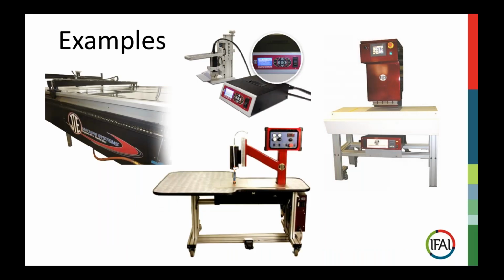So these are some examples of RF welding equipment used in industrial fabrics. The machine on the left is actually a cutting system. Because we have a little bit of core competency in cutting and welding, we developed an XY cutting system that you load the pattern into. It cuts around the pattern, and at the same time, it's welding or serging the edges. This is being used, for example, in an extreme sleeping bag application where they needed to serge their batting in nylon material prior to taking it to the sewing station.